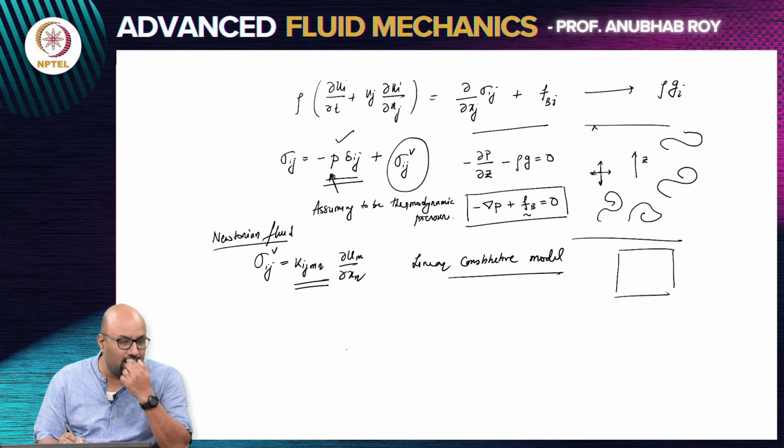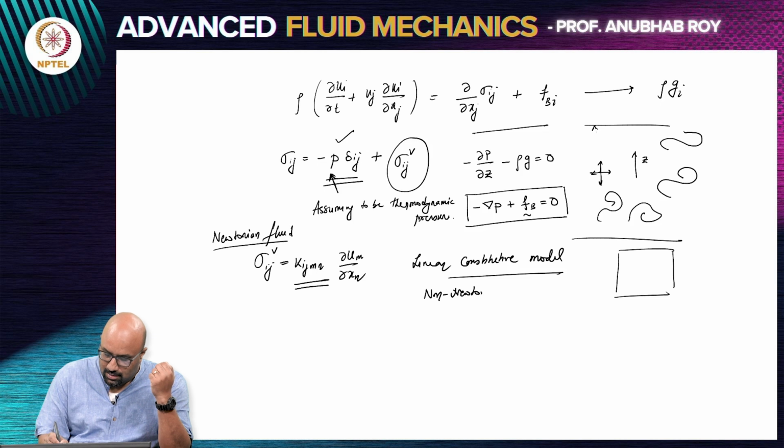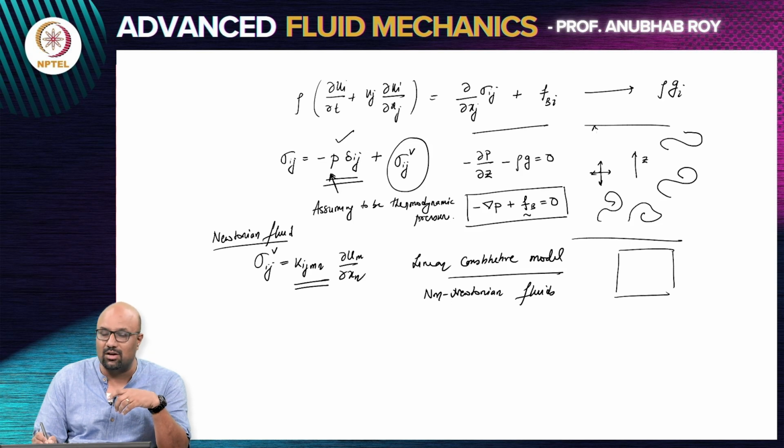So, that automatically tells you that whenever you hear about non-Newtonian effects, when you read more about fluid mechanics, when you read more research papers on fluid mechanics, when you come across people discussing fluids and you hear the terminology non-Newtonian fluids, the first thing that you would realize is that the linear relationship between stress and the rate of deformation is no longer applicable for such scenarios.